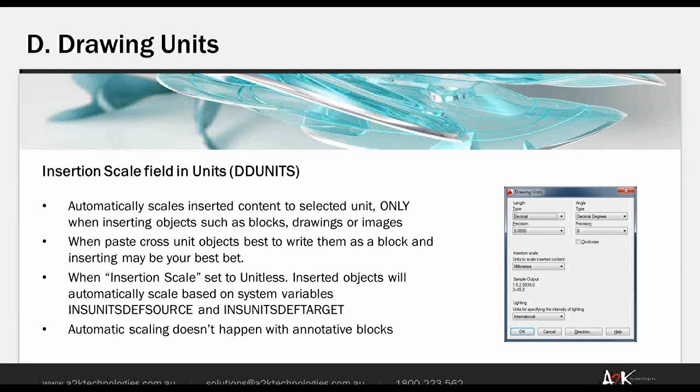Important note: the automatic scaling doesn't actually happen with annotative blocks, because it's the annotation scale that controls the scaling of the block. So if you find that you're inserting blocks into other drawings and the scaling doesn't happen, then check to make sure it's not an annotative block.